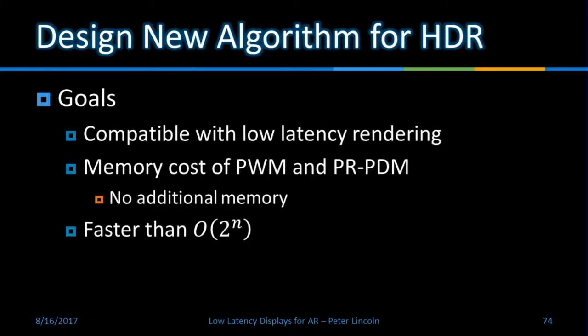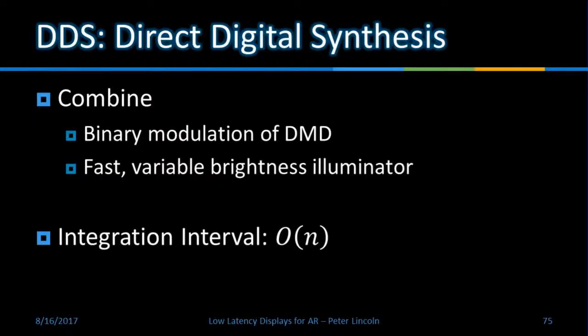Well, we need another new algorithm for controlling the display. We want it to still be compatible with low latency rendering. We want it to still have the zero additional memory cost. And we need it to be faster than exponential time with regards to the bit depth. So introduce direct digital synthesis, DDS, which combines the binary modulation of a DMD with a fast variable brightness illuminator. And with this system, we were able to get an integration interval that was linear with regards to the bit depth. So let's take a look at what the algorithm looks like.